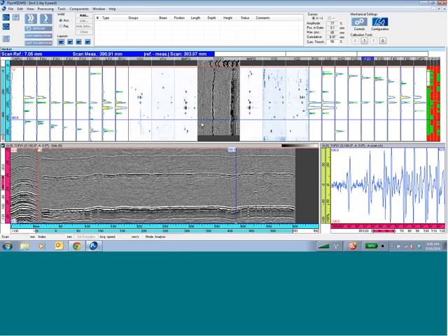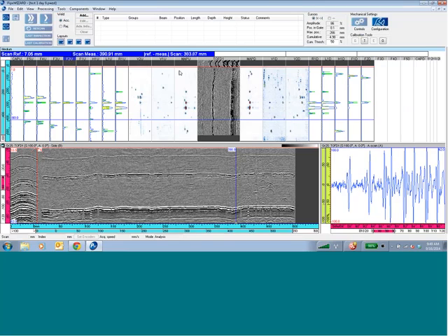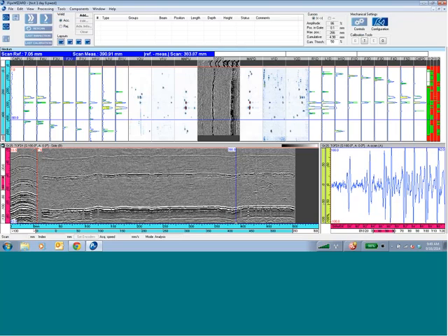If we look at the after effects, here's a pretty typical display of the data. Here we have cap, different fill zones, each individual zone. We have some volumetric channels set up in a B-scan type imaging. We have a TOFD channel for volumetric coverage, which is also displayed here. And then basically the same thing for the downstream. So all this would be one side of the weld. This would be the opposite side of the weld. And then we have some couplant channels here that are going to measure.